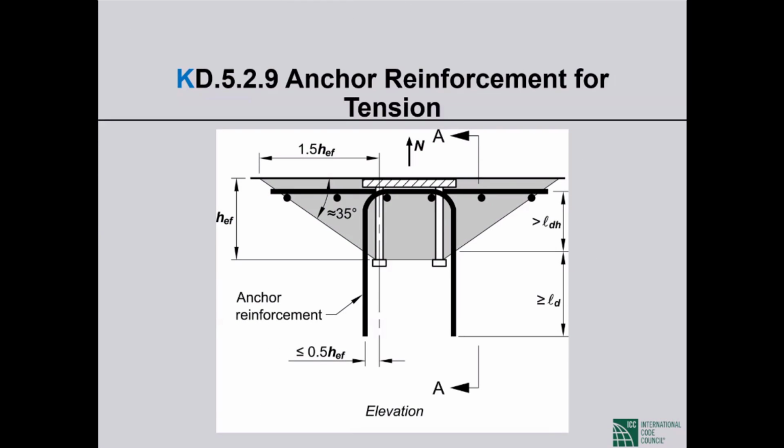So this is very common anchor reinforcement in tension. We have a group of 4 anchors. You see two, the other 2 are into the screen. There is a stirrup or whatever you want to call it in front, and there is one at the back. This piece of reinforcement is developed on this side. This is the failure plane. The shaded area of concrete is what breaks out.